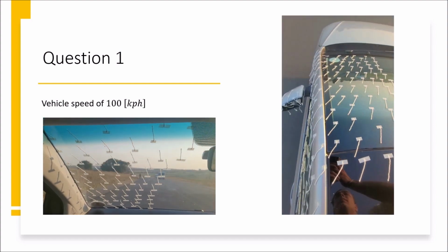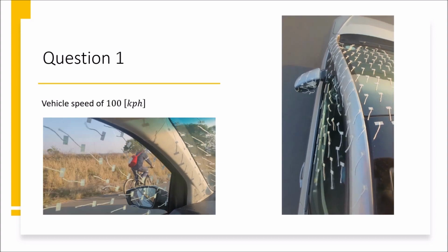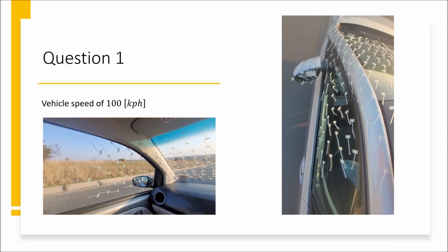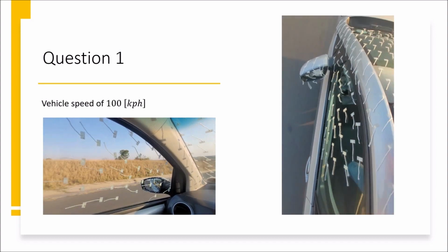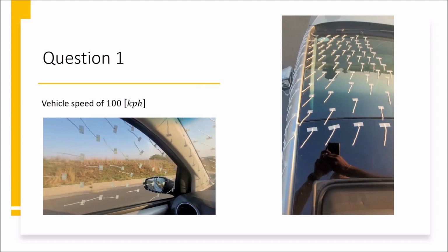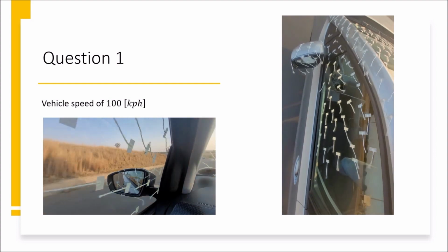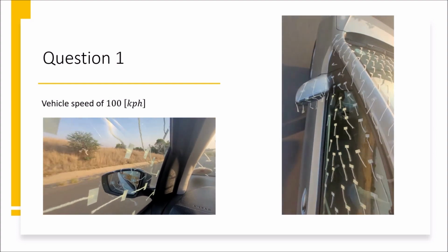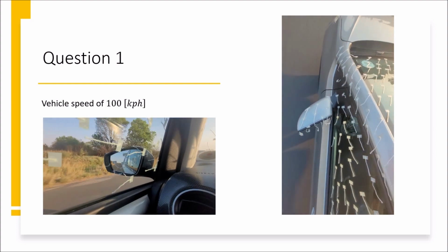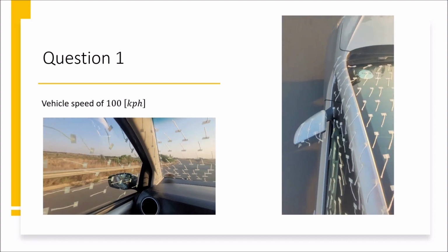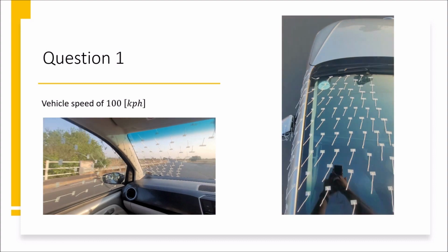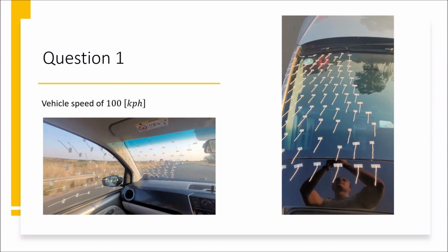The turbulent flow around the side view mirror also creates a noticeable amount of wind noise and reaches the inside of the cabin. It also affects an area of the flow on the door and side panels of the vehicle behind it. The flow between the side view mirror and the body of the vehicle is highly turbulent. This can be seen by the tufts moving in an extremely radical manner, as well as the tufts actually unwinding into individual strands at the tips after driving a while.